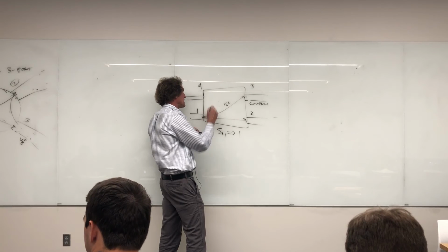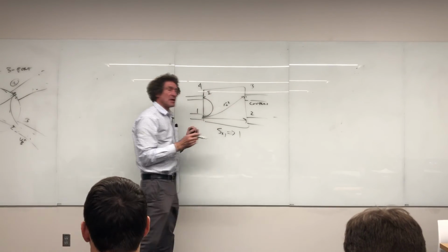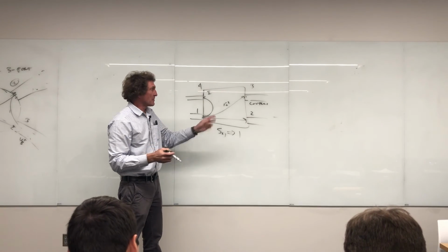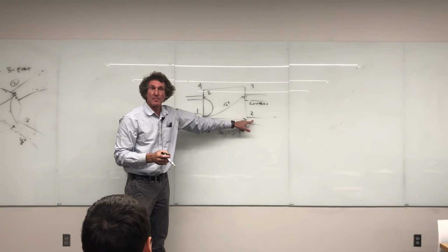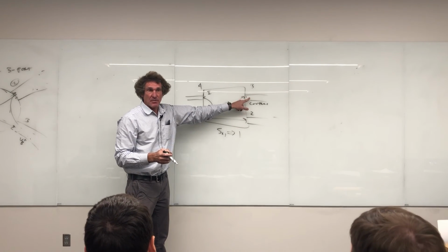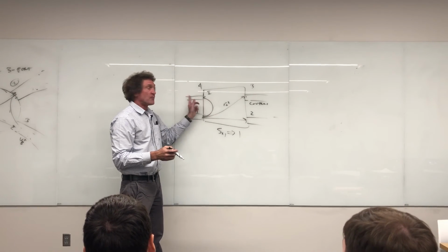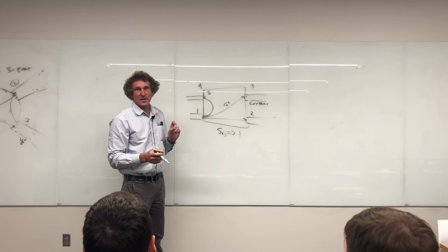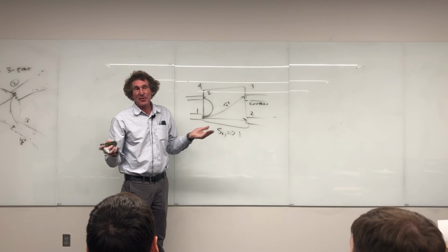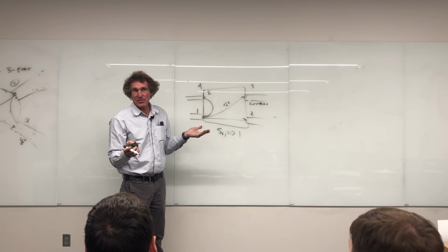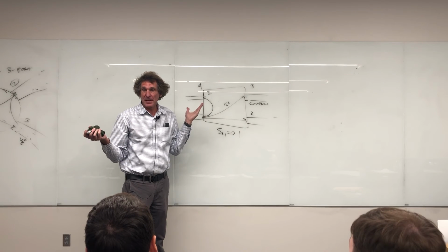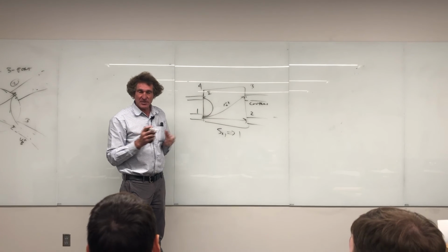And then there's the isolation port. He uses I there. But again, the designations you worry about is you want to look at S. For this, coupled is S21. Follow me? This is S31, right? This is S41. And in S41, it's very high attenuation. Why you use that, I don't know. I don't ever use that. Anytime I'm doing one of these things, if I don't need anything out, I'll just short it out. But if you look in there, you're going to see he talks about this.